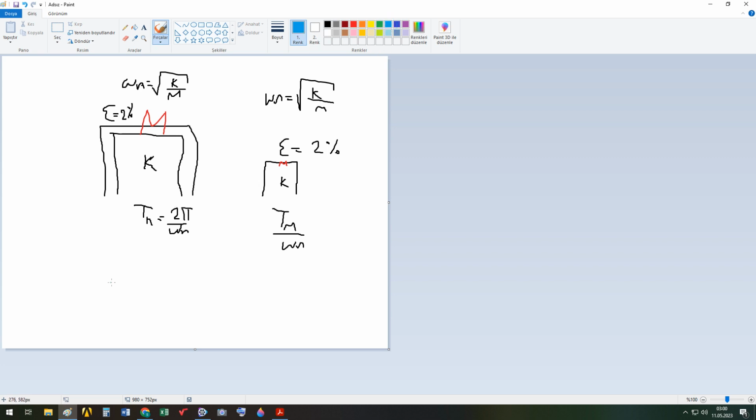They are adjacent to each other. And the ground acceleration, because of the same earthquake, is the same. Their floor displacements at any time will also be the same. For example, at time 2 seconds, this is equal to 3 millimeter, so this will be equal to 3 millimeter.